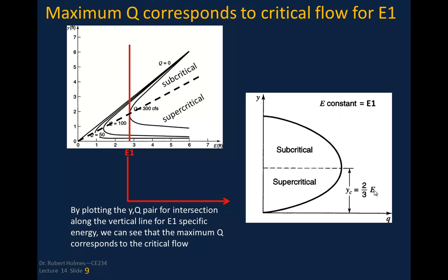If I take that depth and look at that in terms of the specific energy, where I've got depth plus the velocity head, that essentially becomes 3/2 of the depth. That E is equal to 3/2 depth. If I turn that around and take the reciprocal, I'm just saying that the critical depth, YC, is equal to 2/3 E. So there's nothing big there. That's just something I've shown you already when I looked at specific energy at a minimum.